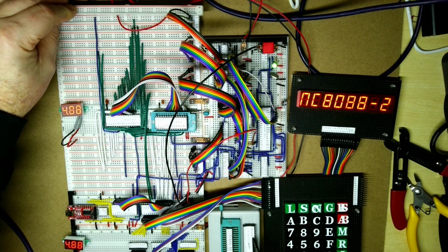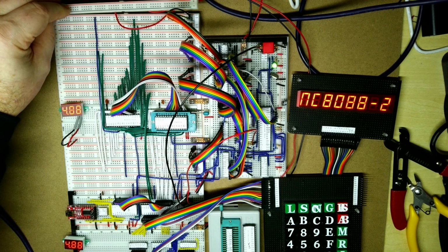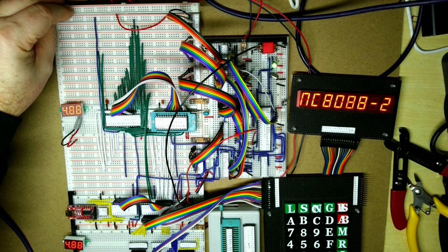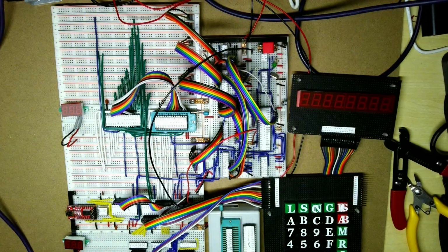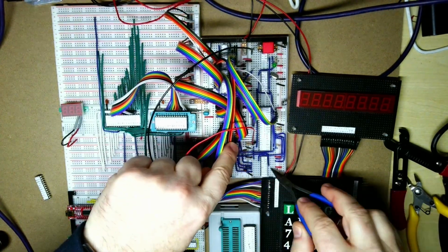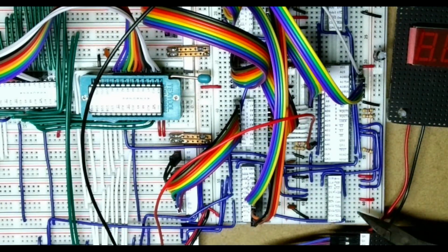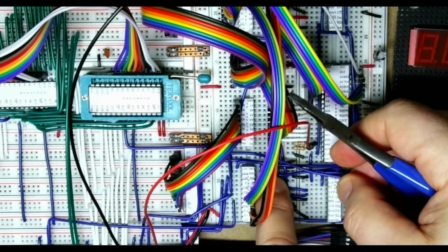And then we'll put in the new EPROM with version 3 of the monitor and see whether or not that works. So I'm just going to wire this up. When we come back, we'll be ready to switch on and see if it works. Just plug in the new bus rail, which will be memory read, memory write. Take out the old PLD and the new program version. Now we're taking out the memory write and putting in the IO read, IO write into the PLD.